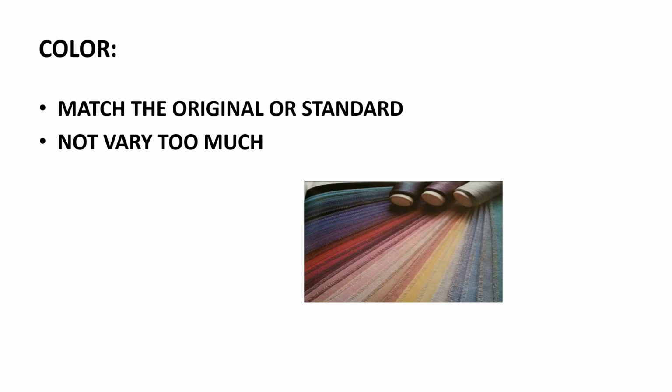So that is the reason that while choosing the color, or matching the color to the standard of the sewing thread during the dyeing operations, we have to take utmost care that the matching is done perfectly with the sewing thread and the standard or the fabric for which it will be used.